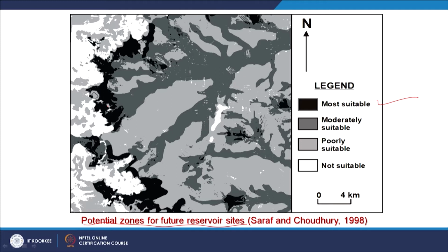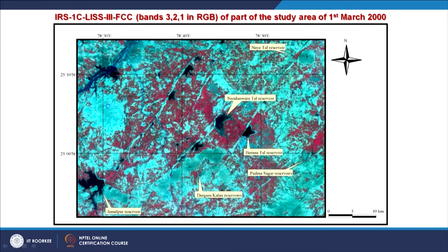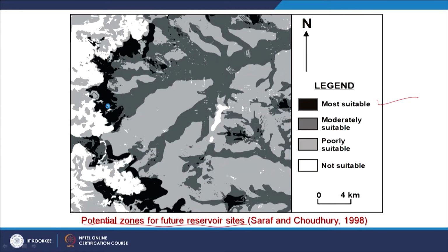So, just at the edge of those higher grounds, because we have learned through that blue reservoir or Sironj reservoir that if it is located on higher ground, it will have a large benefit area relative to the submerged area. That knowledge we developed, and based on it we can develop such maps. These are nothing but GIS based modeling: getting information, arranging it in different layers, giving weightage, and finally coming up with two outputs.